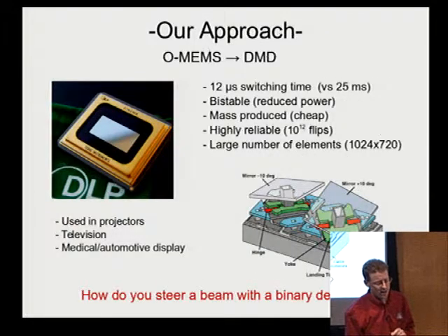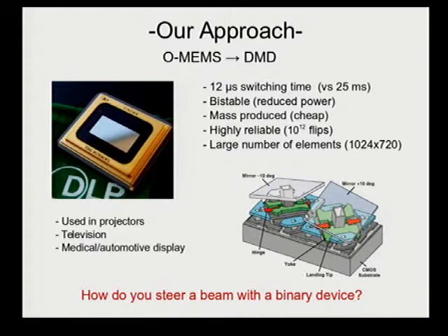But there exists another type of MEMS device that is much faster and more reliable than the gimbal system. And that's the Texas Instruments DMD. DMD stands for Digital Micromirror Device. On such a DMD, the mirror can flip into two bistable positions. It is digital, as its name says. And they can flip in a matter of microseconds. This is three orders of magnitude faster than the gimbal, which takes milliseconds to flip.